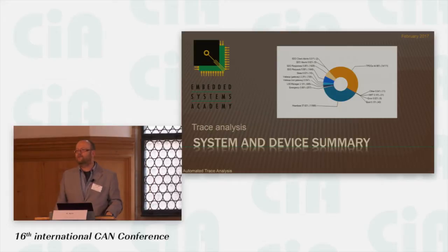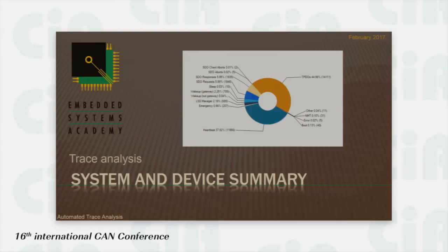So that really shows you that there's still a lot of room available for other communication, because the heartbeat comes stable at 200 milliseconds from devices, and the overall bus load we saw never really went much beyond, I think, 10 or 15%, so there's still quite a bit of room for other communication.